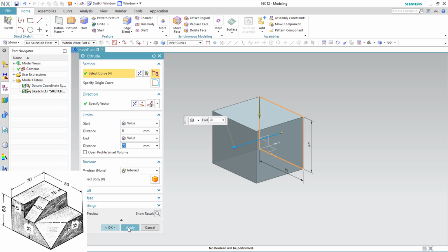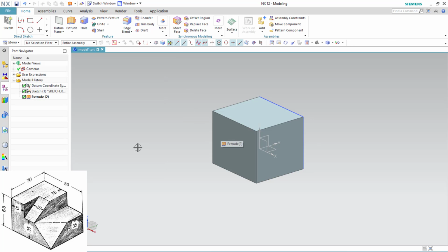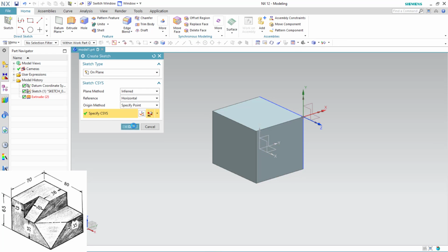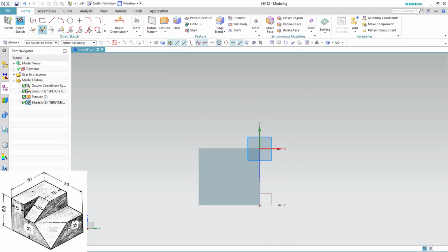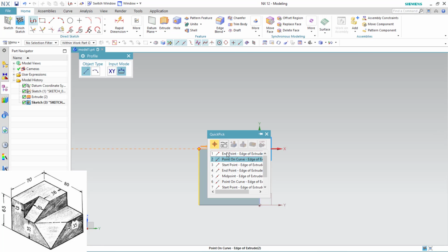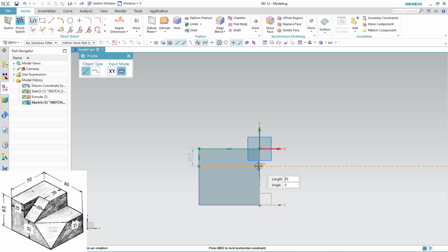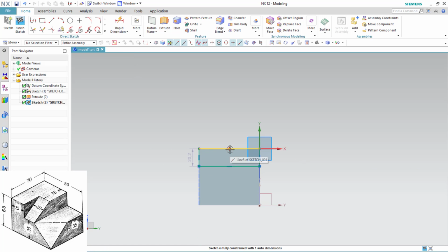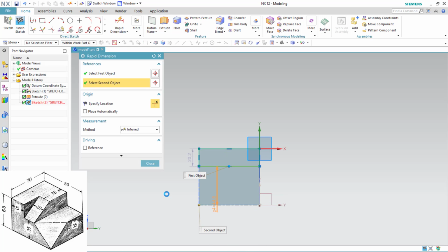Yeah, next thing, I'll select the side face to draw the cutout. First cutout is normal one. Yeah, complete rectangle I'll take this time, because from my right to left side, if you see the sketch isometric view, first it is kind of rectangular cut. The dimension from the bottom to the edge he has given 35.